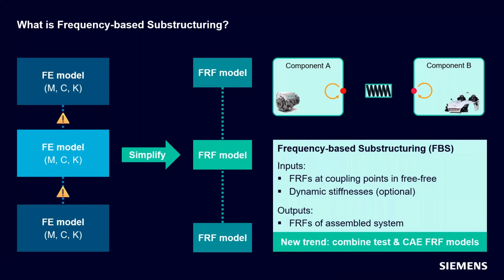Essentially, we're going to collect FRFs, simulate or test FRFs between all of the coupling points, the inputs and the outputs of the structure, whatever those might be. And we're always measuring or simulating in free conditions. So we never want to have them constrained or bolted down or anything like that. If we have mounts in between our components, up here, I'm showing component A is this electric motor. Component B is maybe the vehicle body that we're going to put it in. And there might be some elastomeric mount that goes between those two.